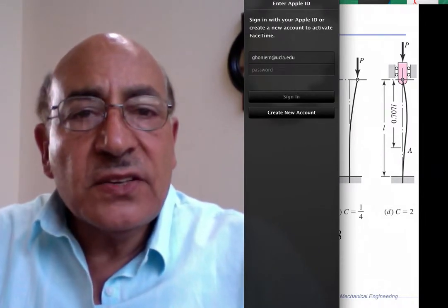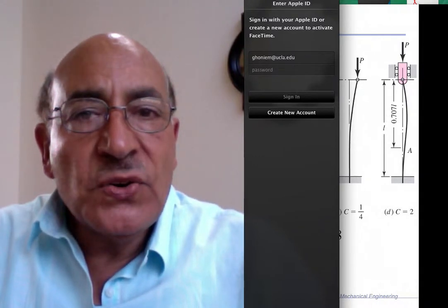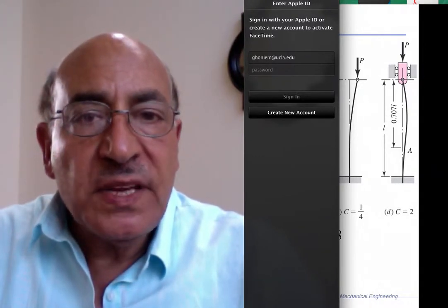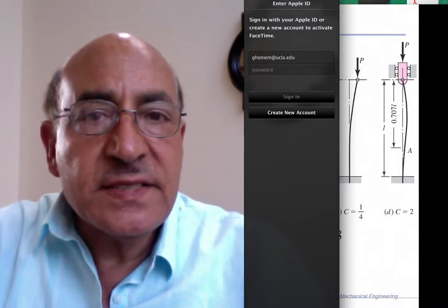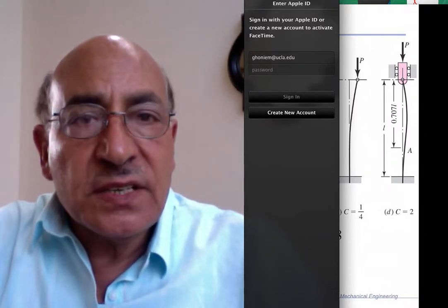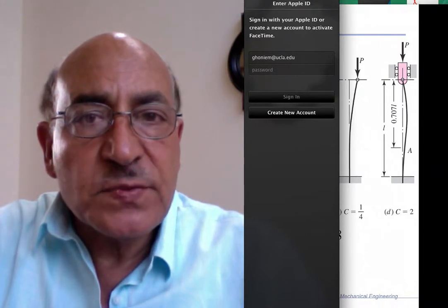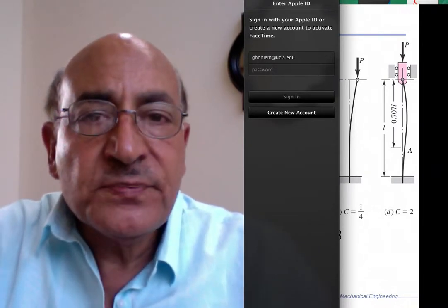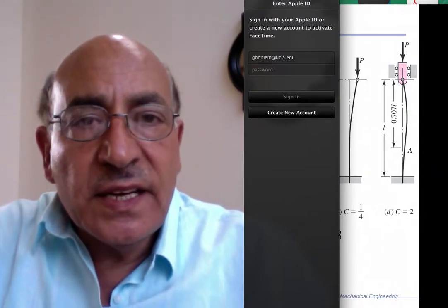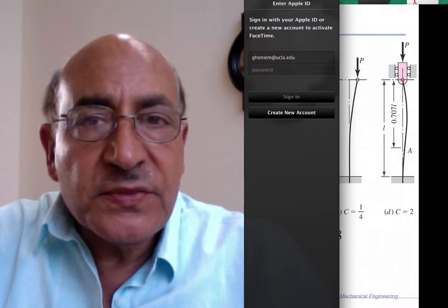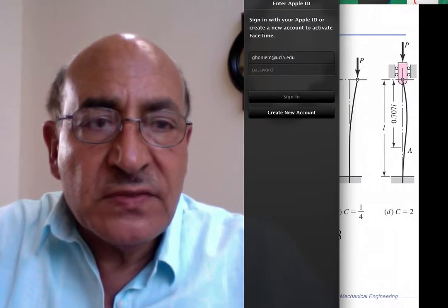And the critical buckling load, the idea is very simple: we know that the curvature of the beam is proportional to the local moment on any section. So the curvature is the second derivative of the transverse displacement, y double prime. If the moment is somehow related to y, then we have to study whether the moment will increase with the deflection or decrease with the deflection.